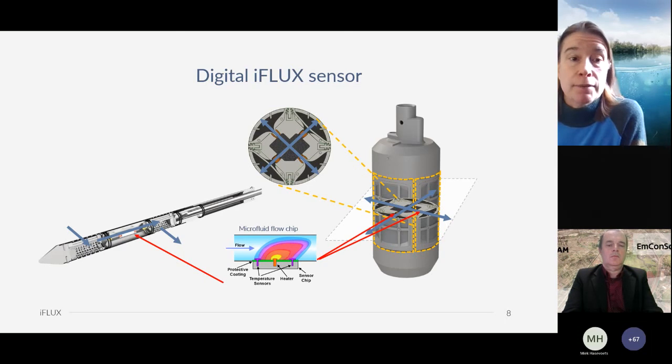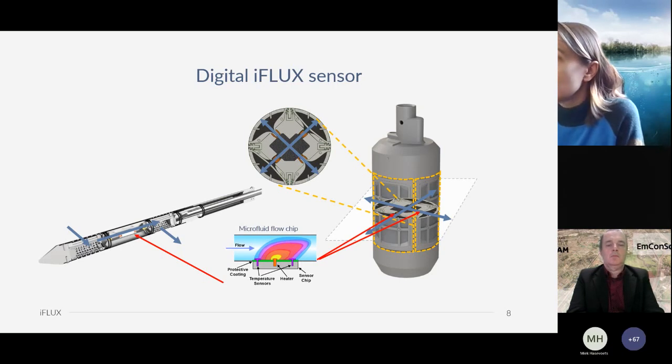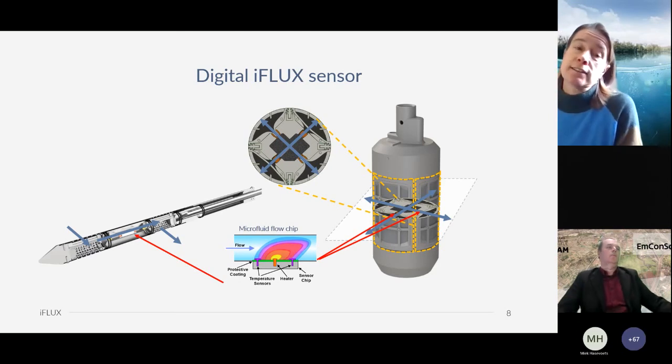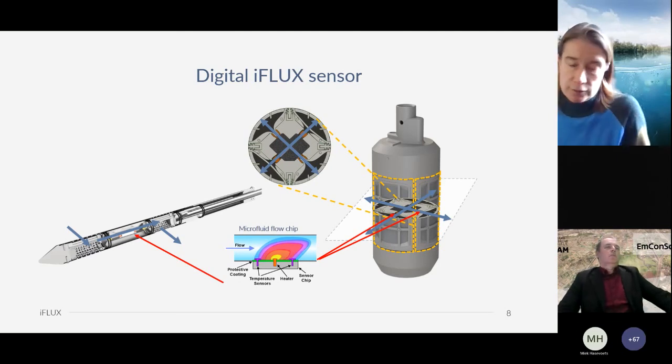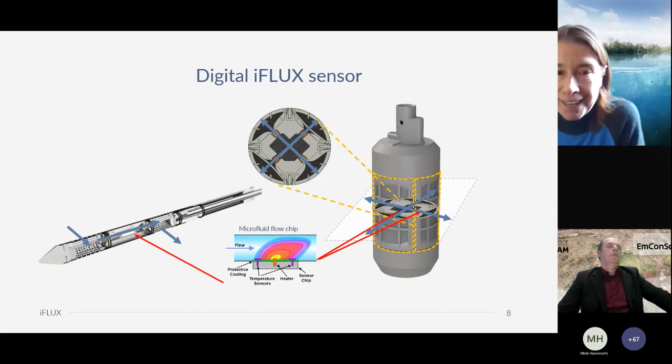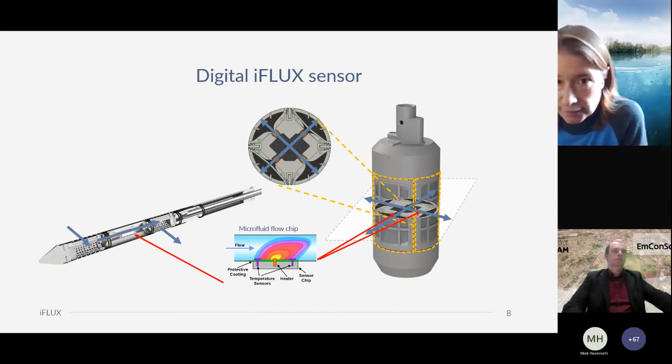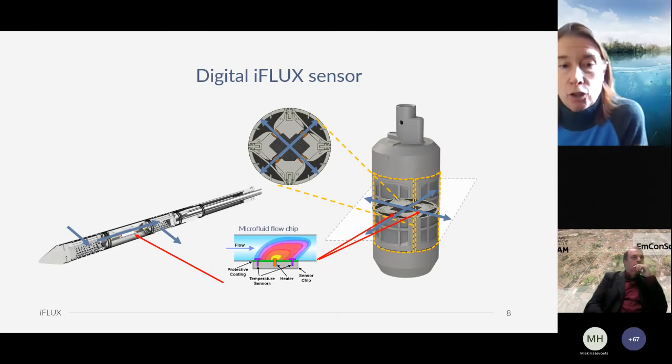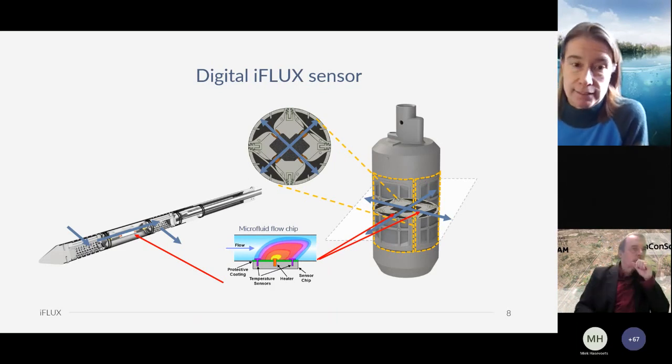The vertical sensor can be installed immediately in soil, while the probe for measuring horizontal flow always needs to be installed in a well. For the digital sensors, it's not yet adjustable to the size of the different available wells on site. Actually, we have a dedicated pre-pack filter which allows us to easily install this digital sensor.